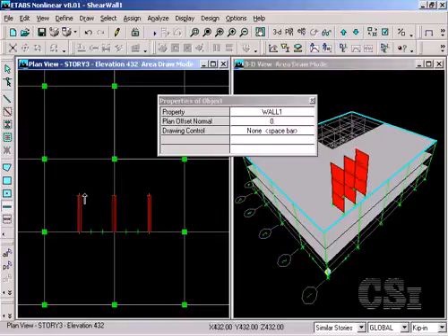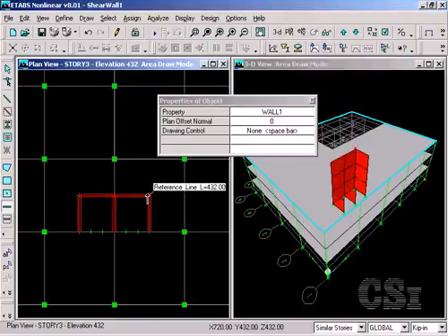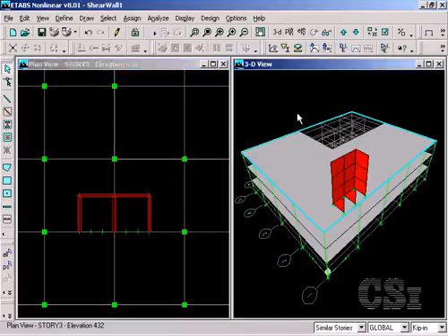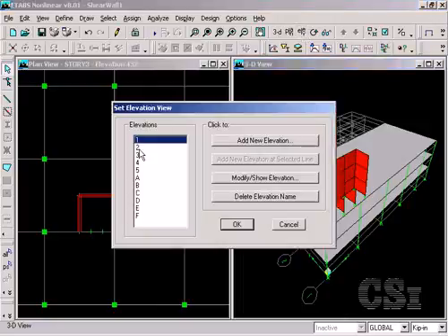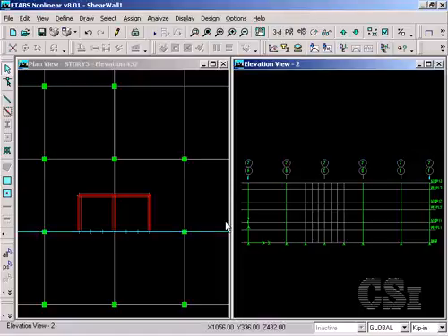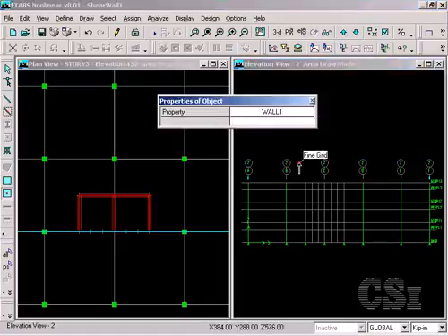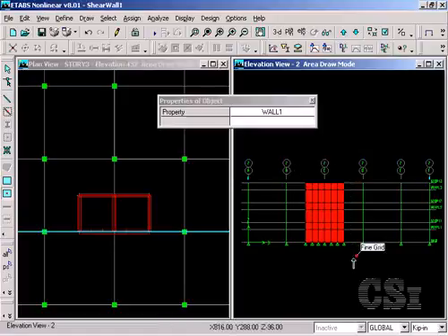Note that we have drawn the back wall's 2 elements, and although this is not necessary from an analytical standpoint due to ETABS automated line constraints, breaking up this wall gives us more flexibility later in the design phase. Switch the 3D view to an elevation view along grid line 2, and click on the Create Areas at Click. Draw the entire wall by using the selection box technique.